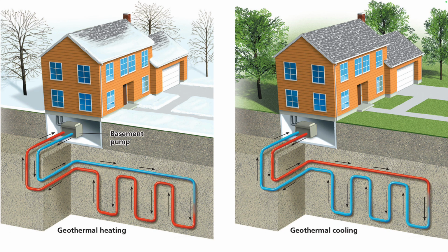Here we see a geothermal heat pump, which can heat and cool homes almost anywhere in the world. This kind of system uses the temperature difference between the Earth's surface and underground at a depth of around 10 to 20 feet. At that depth, the temperature is typically 50 to 60 degrees Fahrenheit or 10 to 20 degrees Celsius year-round. The buried pipes contain a fluid that absorbs underground heat in the winter and moves it into the home. In the summer, it works in the opposite direction. It extracts heat from the home and stores it underground.